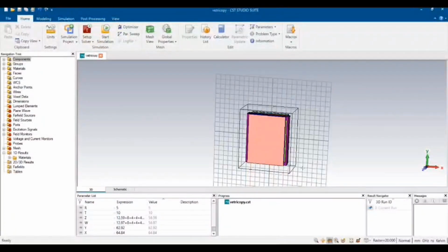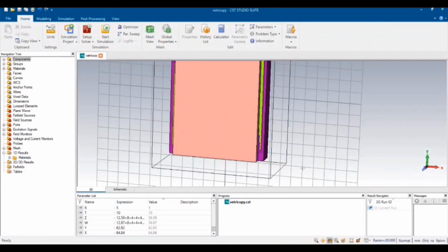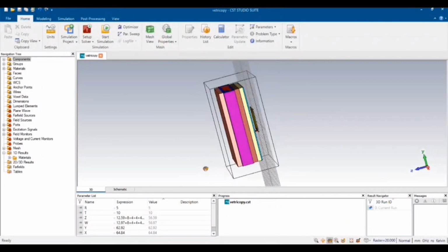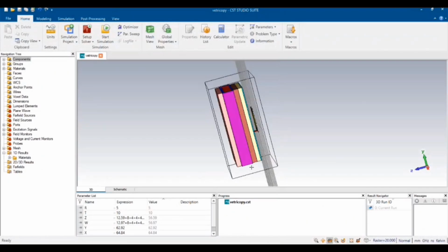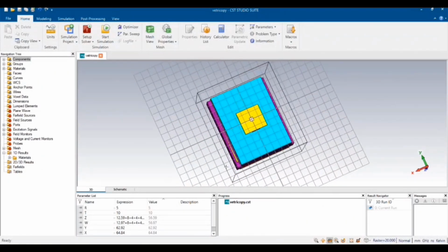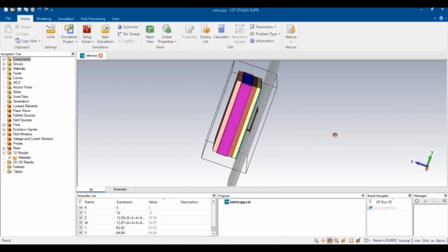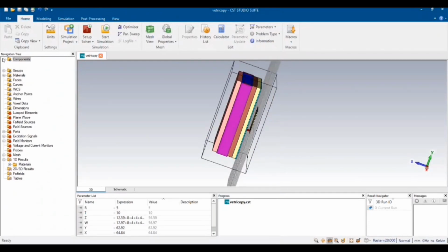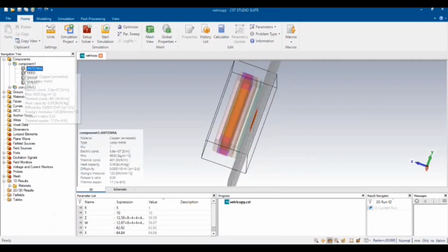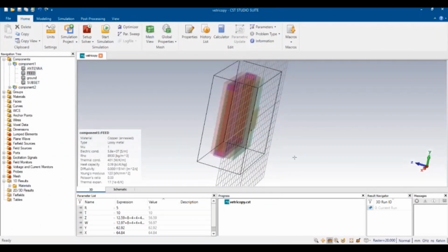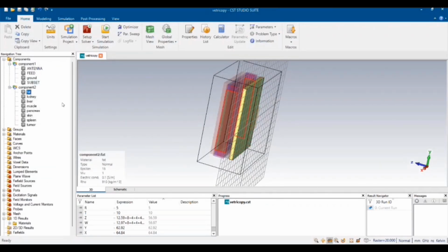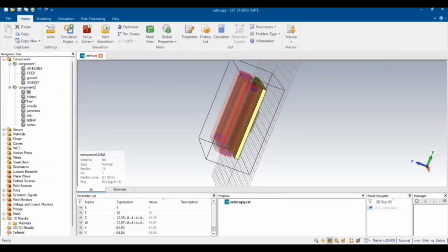Now, to create a realistic human pancreatic phantom in the same software, CST Studio, a structured approach is followed to design, simulate, and analyze the electromagnetic response of both healthy and tumor-affected pancreatic tissues. The primary goal is to construct a 3D model that accurately represents the pancreas along with surrounding organs such as liver, kidneys, spleen, muscles, fat, and skin. Each tissue component is assigned specific electromagnetic properties including relative permittivity, conductivity, and density based on established biological data.